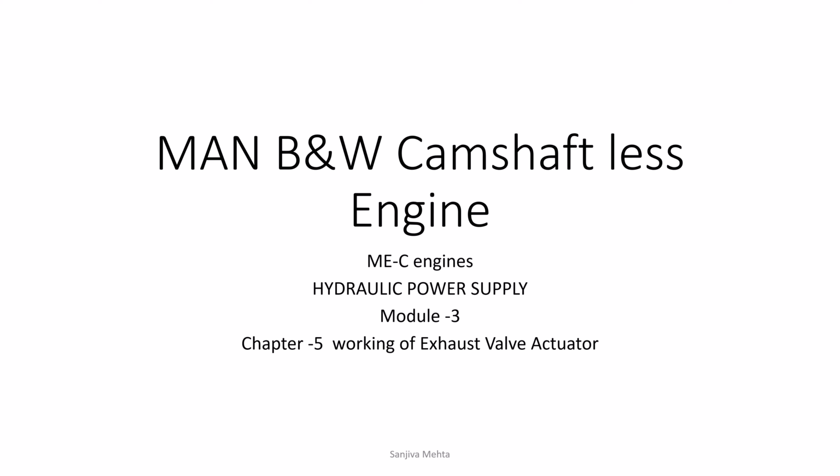Here, module 3, we will discuss hydraulic power supply. Hydraulic power supply, because the actuation of the fuel pump, exhaust valve, and cylinder lubrication is all carried out by hydraulic pressure, not by mechanical force as in the conventional engine, because there is no cam, no camshaft, no drive shaft, nothing. So naturally hydraulic pressure is used.